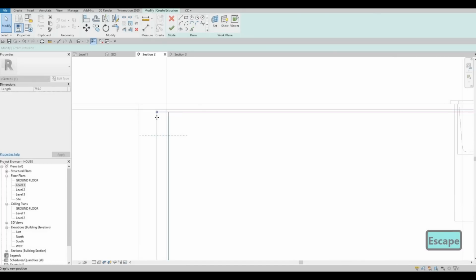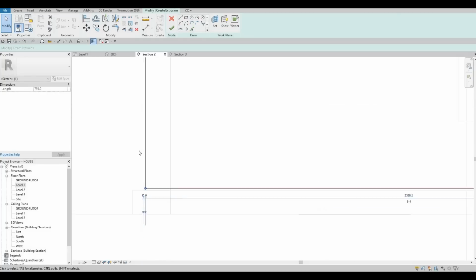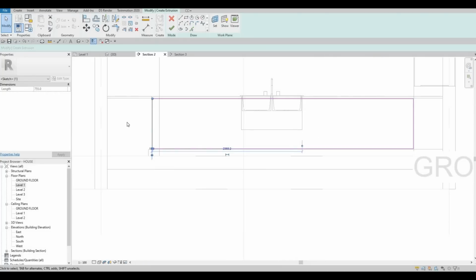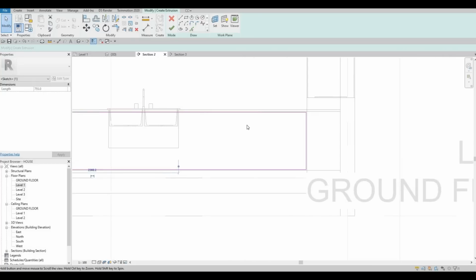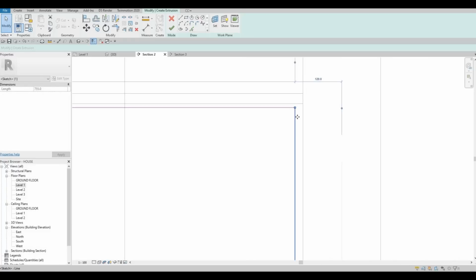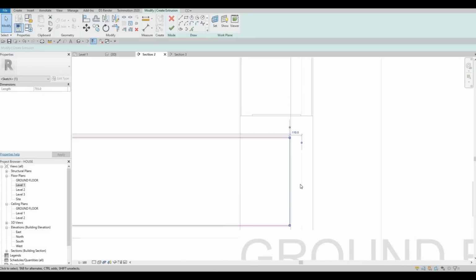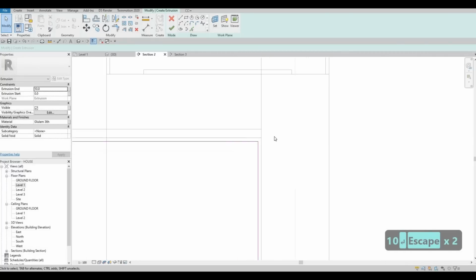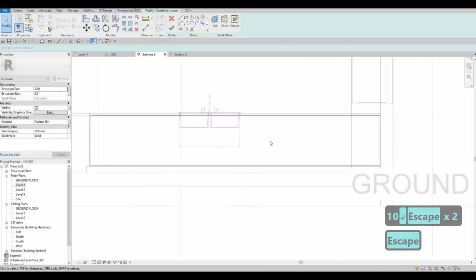Here I'm going to add it on this side. So this is our L shape, and this is the side where the cabinet is, and this one is all the way to the end. By using wireframe, you'll be able to see what's behind. So right here, we can select this one and then put it to 10. So it looks like it's exactly where we want it to.